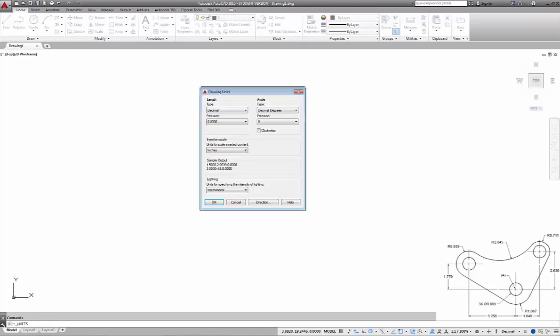We look at our drawing, and our drawing says that we've got 3 decimal place accuracy. So we need to set our accuracy for our decimal dimensions to 3 decimal places. Whether it's millimeters or whether it's inches, makes no difference. You set the decimal precision, and you determine whether it's a millimeter drawing or an English drawing. Only at the very end, when you're actually scaling it to plot, does it have to come into serious play on whether it's been created as a millimeter drawing or an inch drawing.